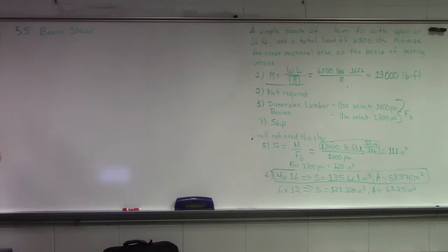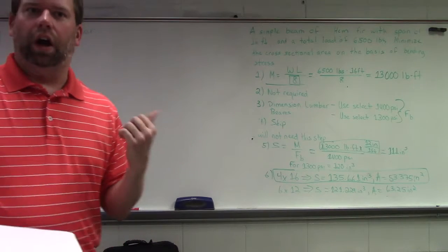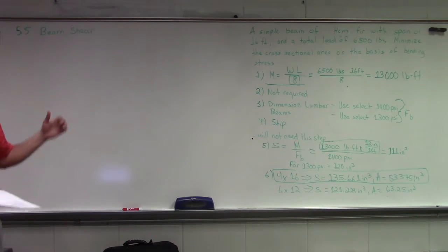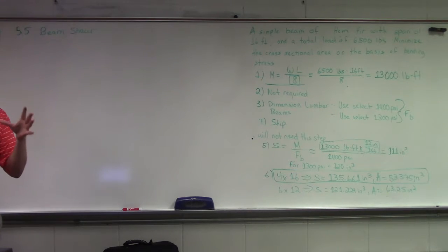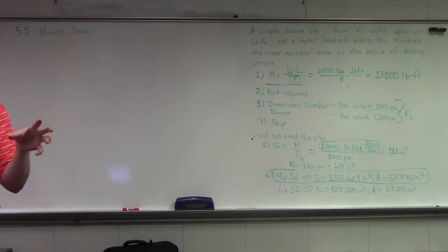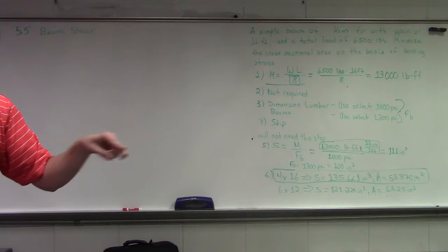1 is beam shear. Generally speaking, our wood is going to be fairly weak when we're dealing with shear, specifically on our bearing areas, towards the end of the beams themselves. They typically want to try and split horizontally.